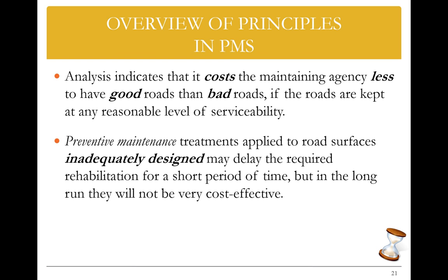So one more time, typically we tend to spend a lot of money, and this is the old school of thought, on the bad roads and leave the good roads until they deteriorate. But this is the old school of thought. Now we found out that it's good to spend a small amount of money on the good roads to keep them in good condition all the time, so you won't eventually need to spend a lot of money on rehabilitation or major reconstruction. And the way to do this is by following preventive maintenance.